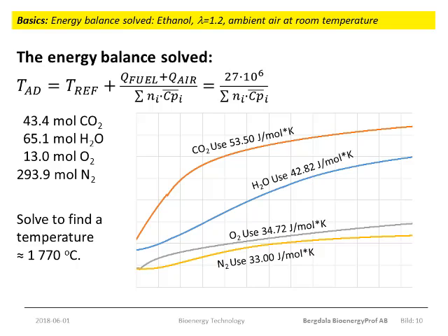There is also another end to the adiabatic temperature. For a continuous and self-sustained combustion, there is a demand that the temperature is high enough. Again, the adiabatic temperature may serve as the first estimate, and one may say that if the adiabatic temperature drops towards 1000 degrees C, then it becomes questionable if combustion can occur at all. With biomass, which often contains significant amounts of water, this may sometimes be a problem.